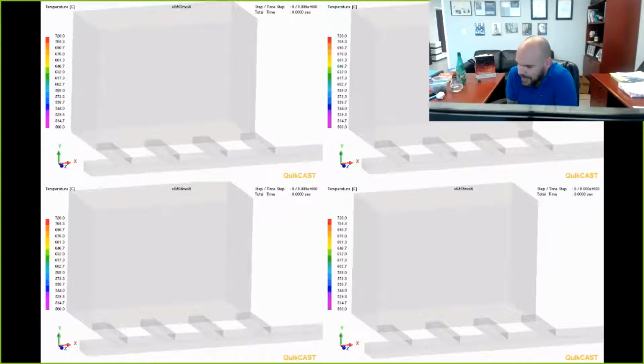If we slow the metal down, it won't squirt through the gates and will result in less in-mold cavity oxidation. And guess what? It kind of worked, right? It kind of worked to the huge detriment. And it kind of worked because, again, what we talked about, it's a manipulation of the continuity equation, this Q equals AV thing. You've got a consistent volumetric flow rate, and you've got an expansion of cross-section, which has a reduction of velocity, right?